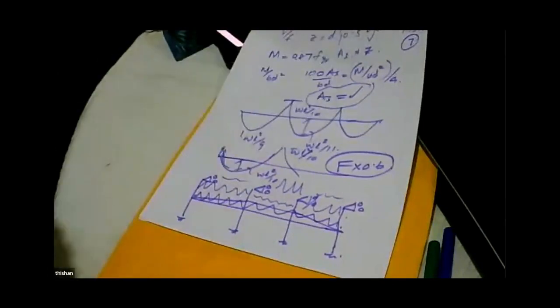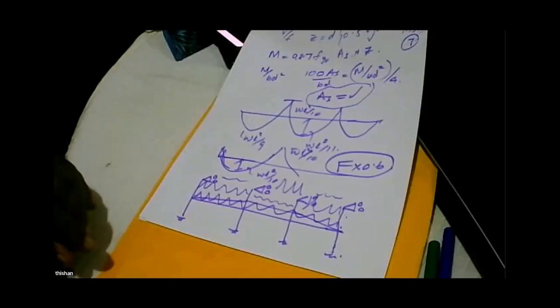So somebody says, okay, I'd like to find the shear. So I find the maximum load multiplied by 0.6. That is the shear force. Somebody asks, what is the shear? I say, okay, it's 0.6 times the full load. On the other hand, I can find it from the bending moment diagram. Once the moment model is there, you can find the shear force diagram as well. Is that clear, Bandhu? Yes, sir. Clear.